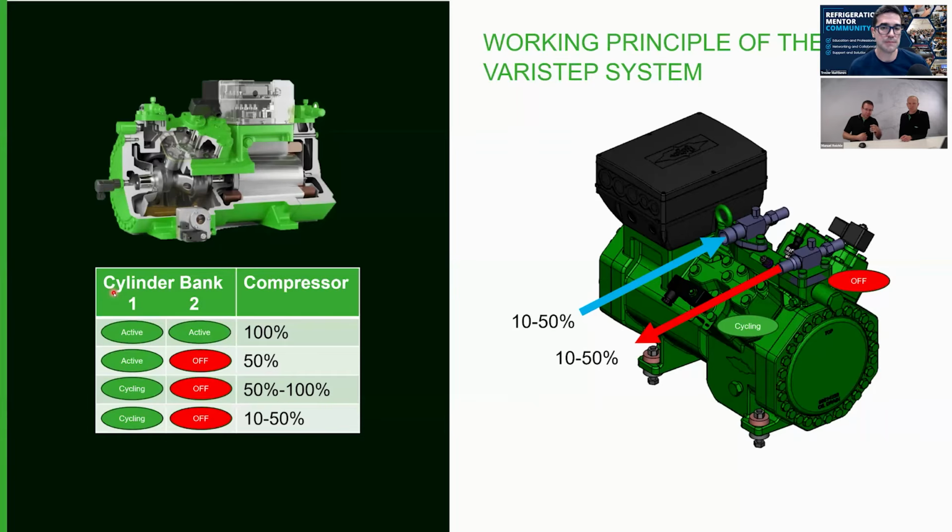Everything is overheating if we run constantly at 10%, the oil will get too hot because there's not enough suction gas flow coming to cool it down. The discharge gas temperature can exceed the 284, and we will not see it. Therefore, the IQ module has a special function to monitor this situation. After a certain time, depending on whether I operated the compressor at 100% before, or at 30%, what was the situation before? The time is always different for how long I can run it at 10%.